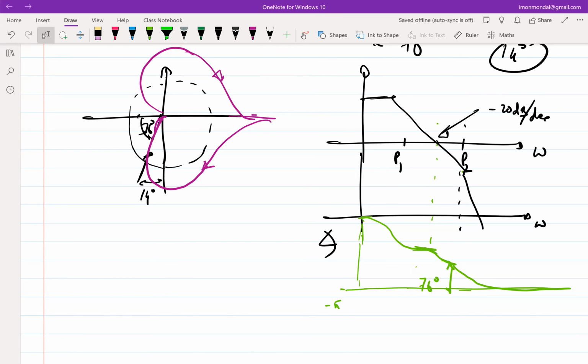Right. So now, what circuit designers did was generalize this. We know all this about critically damped and zeta is valid only for second order systems. But we also know that we cannot have only second order systems. Our systems actually have third order, fourth order, fifth order, I don't know how many poles.